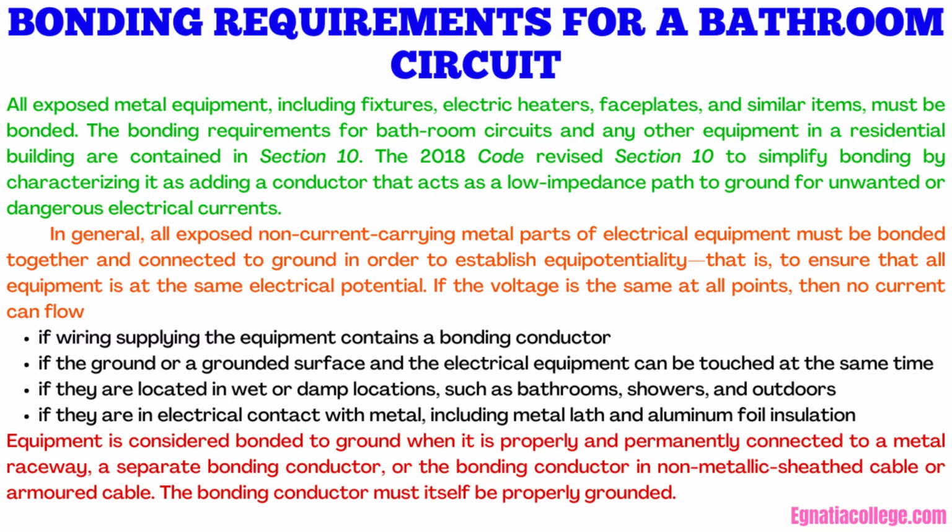In general, all exposed non-current carrying metal parts of electrical equipment must be bonded together and connected to ground in order to establish equipotentiality, that is, to ensure that all equipment is at the same electrical potential. If the voltage is the same at all points, then no current can flow. If wiring supplying the equipment contains a bonding conductor.